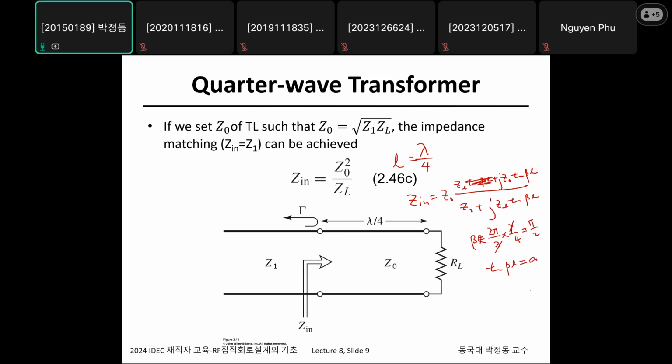So you just divide this by this. So eventually you get G0, and here you have a G0, and here you have a jGL, right? Which is G in. Therefore, what you get is G0 squared is GL multiplied by G in, right? Therefore, required G0 is the square root of GL times G in, right? That's this, right? Okay.